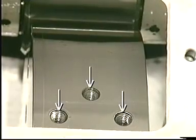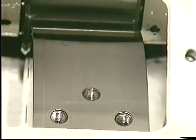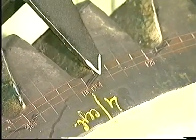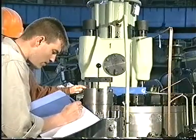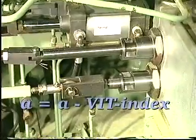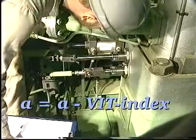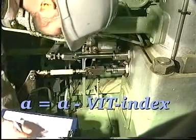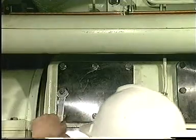Leave the cams to settle for a minimum of 15 minutes and then mount the plugs. Turn the cylinder concerned to top dead center and read the new fuel pump lead. Read the VIT index. If the VIT index is not at 0, the lead must be corrected before it is recorded in the engine logbook. Mount the cover of the camshaft housing.